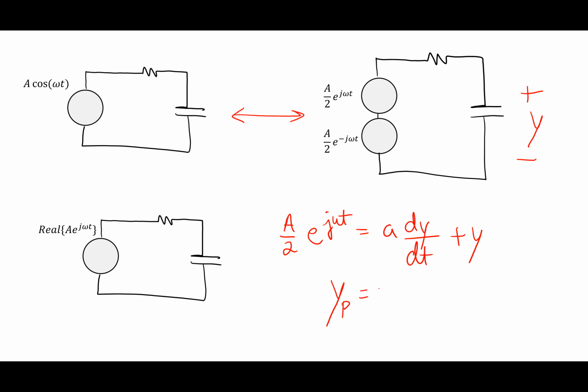All right, so constant is my input. What does my output look like? 9 volts in, I get 9 volts out, right? Constant in, constant out. Cosine in, cosine out. Sine in, sine out. What happens if I put an exponential in? Exponential out. So what I'd see is my output would be B e to the j omega t, like that.